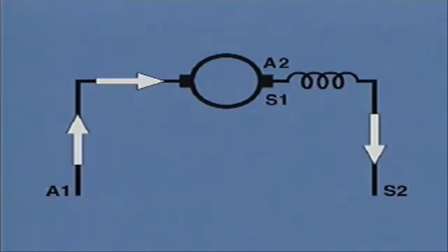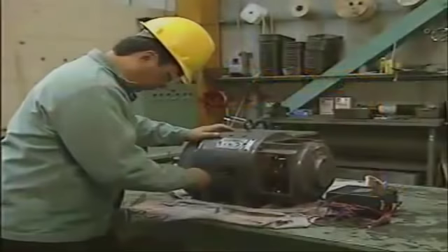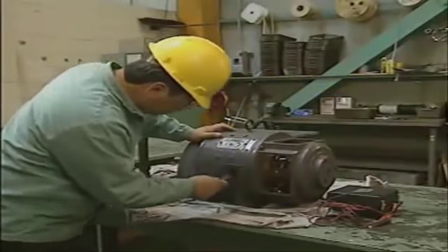The primary purpose of the markings is to ensure that when the motor connections are made, current flow through the motor will be in the proper direction. The same markings are used to identify the motor's leads. So you can also determine what type of DC motor it is by examining its leads.